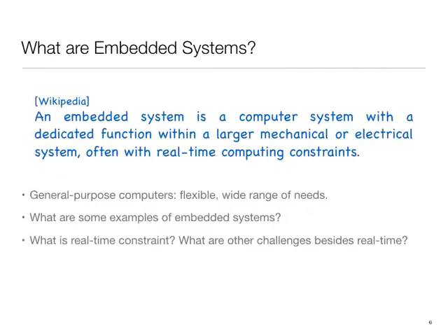So power has to come from someplace, right? And so when you are drawing energy, you're drawing it at a certain rate, and so the supply system needs to be able to supply that current. And oftentimes there is a mismatch associated with that, because it's not simply how much power, how much energy you are using for a particular task, but also the rate at which you are drawing the current. So, for example, if you have a system which is making use of some particular source, it may have a lot of energy, but maybe it cannot supply the current necessary.